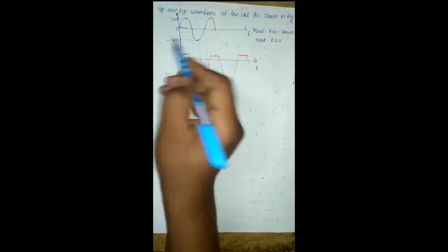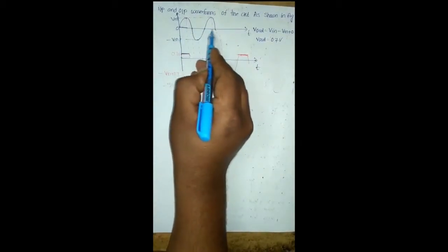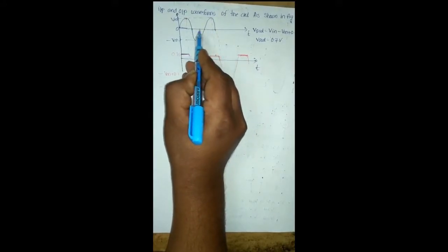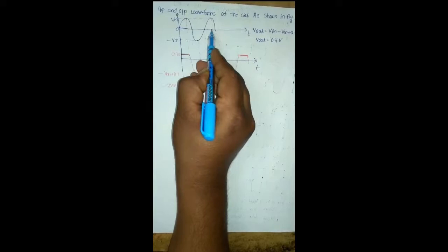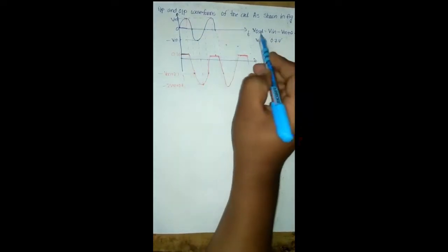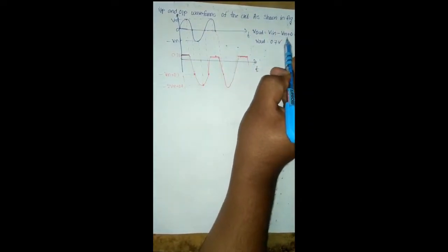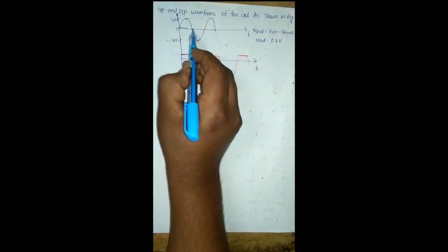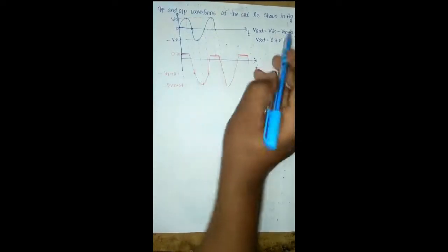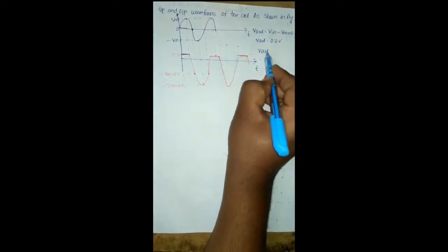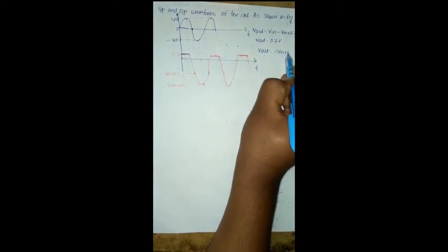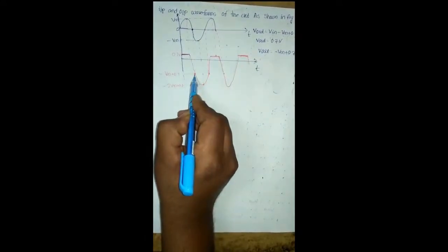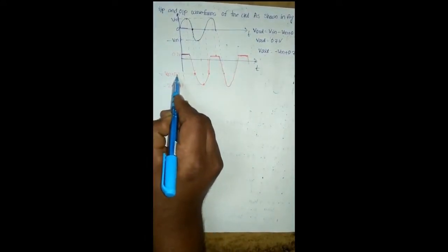After reaching this instant, in this overall duration, the diode operates in the reverse bias condition. Therefore, the diode is open circuited. At that time we get the output voltage equal to Vin minus Vm plus 0.7 volts. For example, if the input voltage of the negative clamper circuit is 0 volts, then we get Vout equal to minus Vm plus 0.7 volts. Therefore, at this instant the output voltage is minus Vm plus 0.7 volts.